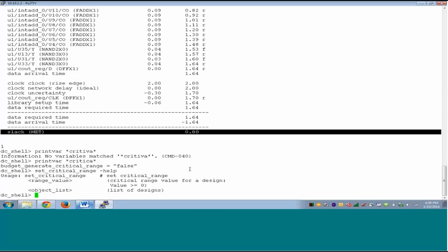Now for some reason, let's say you are doing some trial synthesis. In this case you see that slack is actually 0, right? Some people for special cases may not want a 0 slack. They want some margin, they want the slack to be positive, let's say 100 picosecond or 0.5 nanosecond or something like that. You can use set critical range to control that. This is again an advanced feature used for very specific cases.